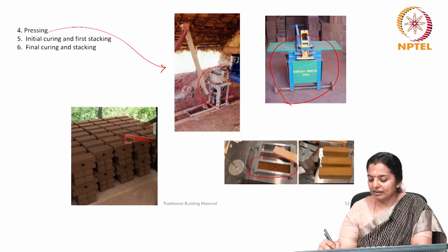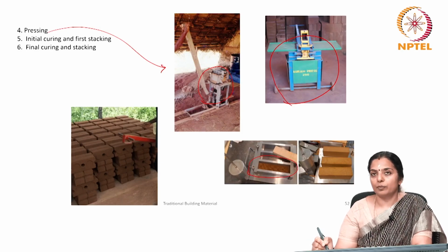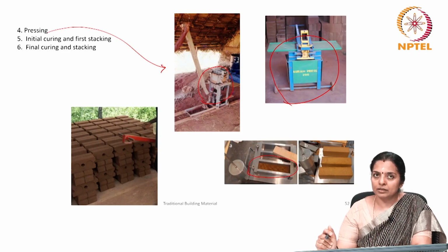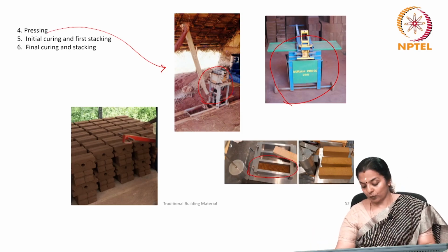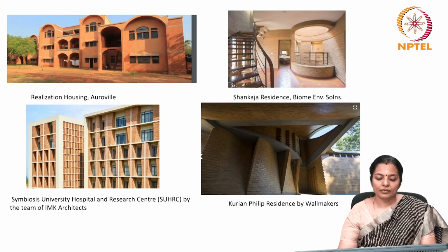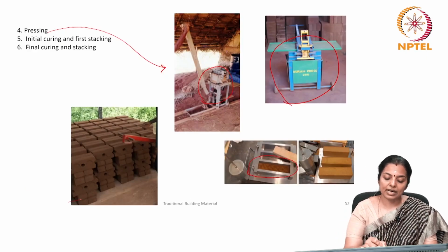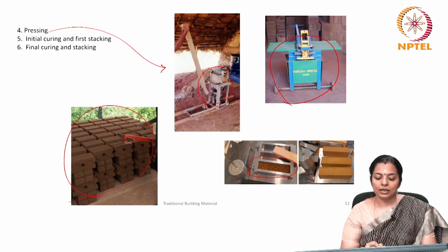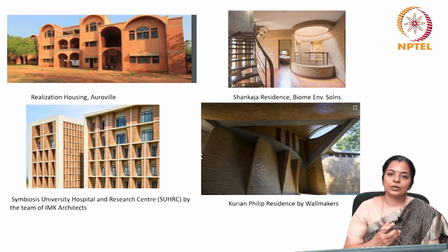Steel molds will give a very sharp edge, and you press these blocks very strong, hard. You press it manually or through machines and keep it for 28 days for proper curing, and then the bricks are ready. Of course, it's important that you stack the bricks properly. After you make the mix, you stack it and leave it for curing, and then you can start using it